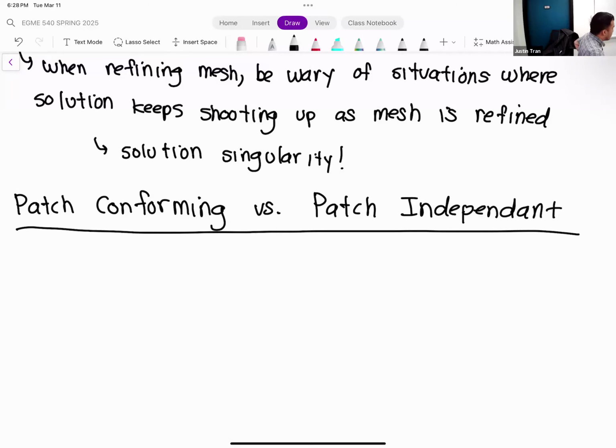If you think back to your ANSYS activities and the method object that we apply on our mesh sometimes, you should see that part of that meshing method is whether you want a patch conforming or patch independent method, right? It's right up there with the element shape and the element order, just that we haven't modified this up until now. Okay. So patch conforming and patch independent are two different meshing schemes, and they revolve around how ANSYS actually produces your mesh.